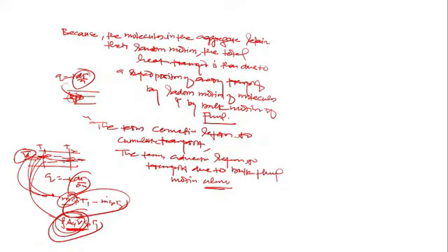So advection means pure bulk motion, like m dot Cp T. I am talking about the mass flow rate. Only the energy transfer, because as the fluid moves, this also transfers energy, since here the temperature is T1, here temperature T2. So when the fluid moves with some velocity, there is also energy transport. Is this clear? Yes or no? Are you getting the point? So this is the transport of energy, m dot Cp T, due to only bulk motion.